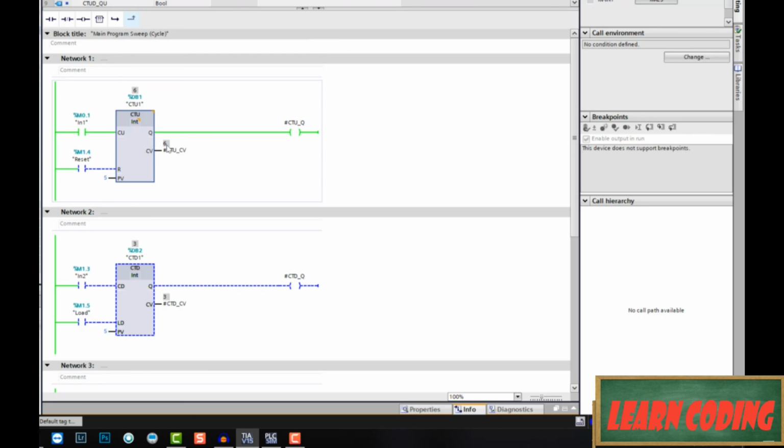So that value is going to go up 5, 10, 20, 30, something like that every second while this is energized. And for things like that, you're going to have a one-shot before your counter, or before whatever's energizing this contact. In Siemens, you can think of the counter as having a one-shot built inside, like a positive trigger built inside.